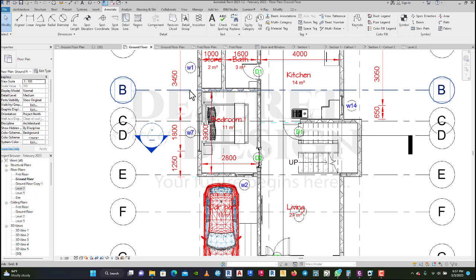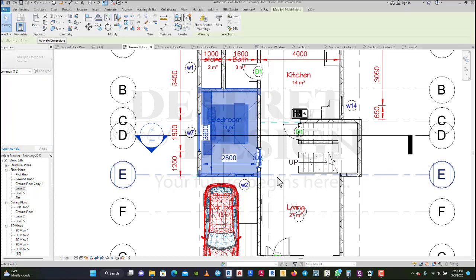So what I want to see in actual 3D is the bedroom alone. So what you do is that you do a box selection of that area. So I'll click and open a box around that area. Do you get it? Now when you finish, it has selected that place. That is the area you want to see in 3D. Then you come to your view tool here, not this view tool. This one here on your modifier, the view.